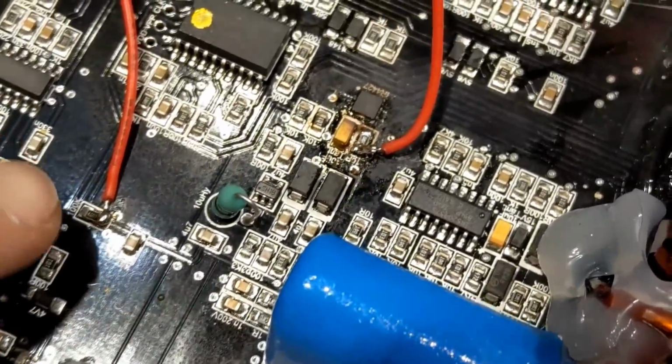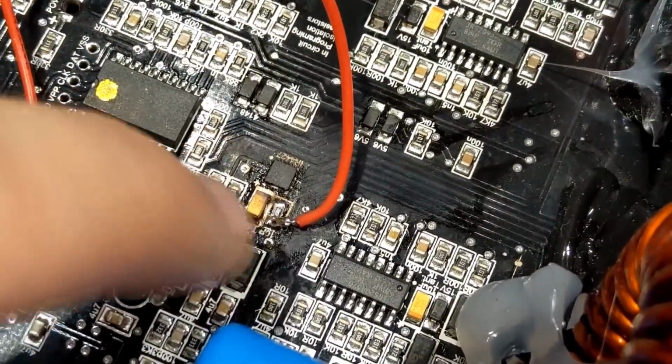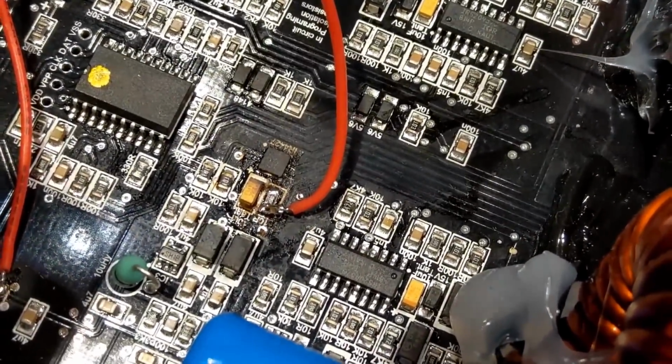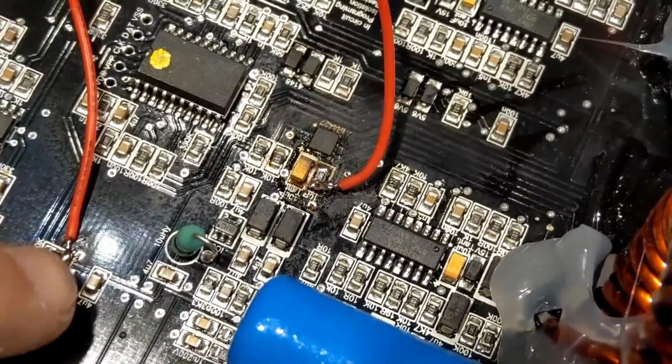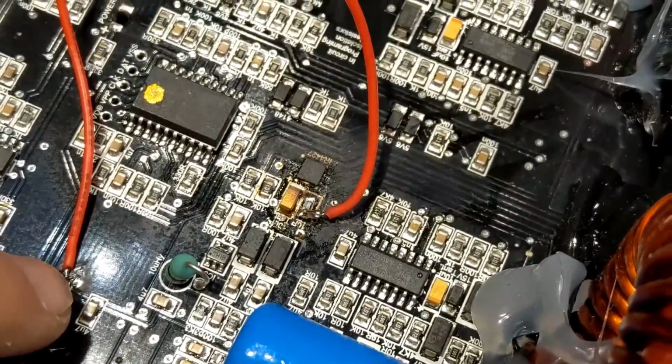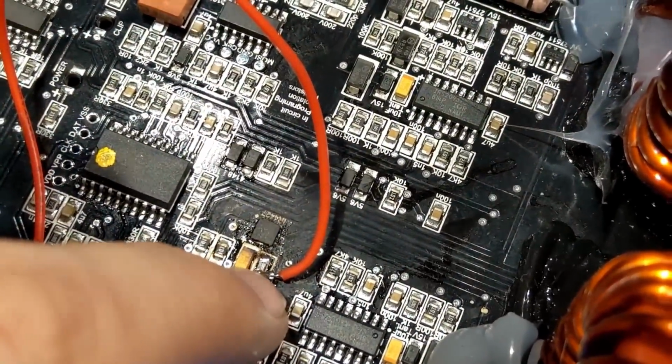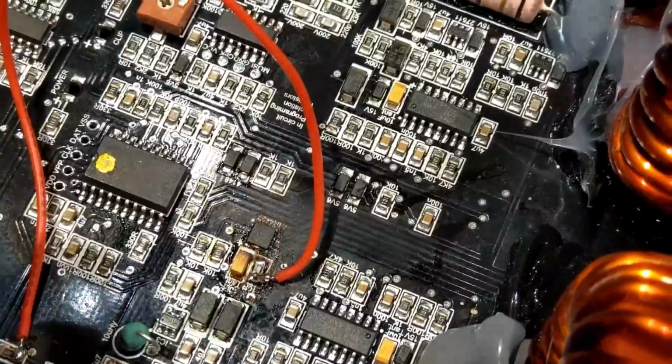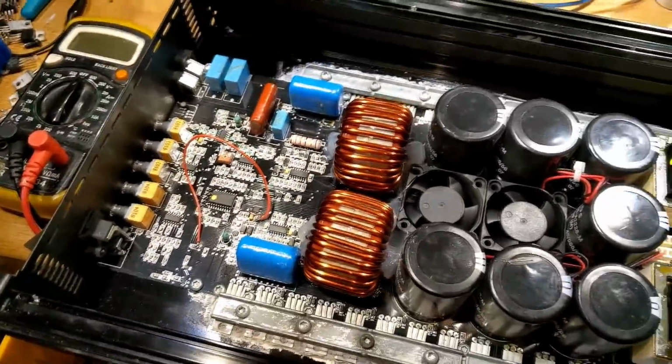There's battery voltages over here, but there's probably going to be a blown trace somewhere, maybe on the underside of the board. So by bridging battery voltage input, which is over here, there's a nice handy version over here, and then taking it round and forcing it into the chip here, the amplifier comes on and performs perfectly fine.